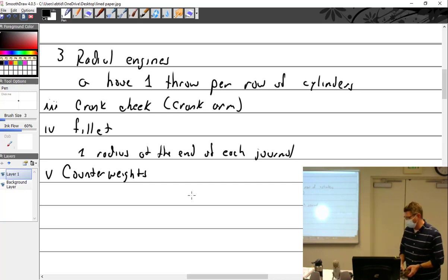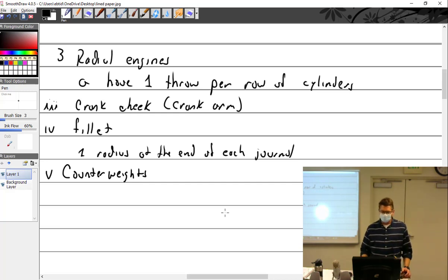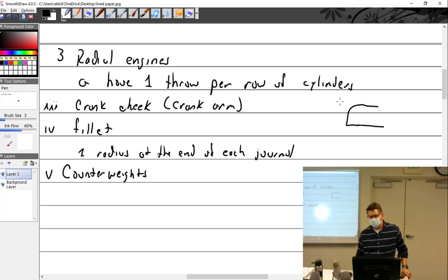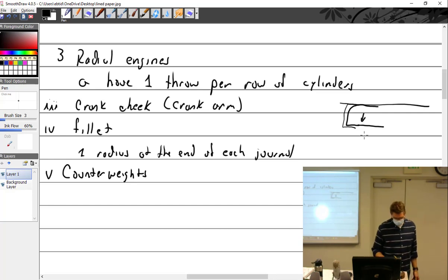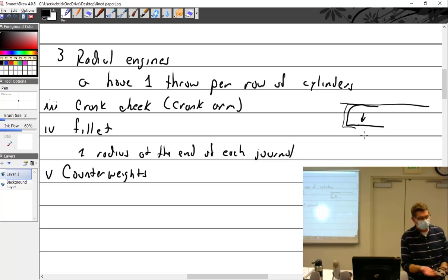If you look at snap rings under a magnifying glass, you will note that snap rings kind of look like this. There's always a rounded edge and a very sharp edge. And the sharp edge, see in this case, the plate would go behind there, and there's a little groove that it sits in, and the sharp edge should have the force going that way for obvious reasons. So in this particular case, you'd have to look at it and know the sharp edge should be facing out, and that goes in. And then there's a space between these little snap rings. You guys probably can't see that real well.